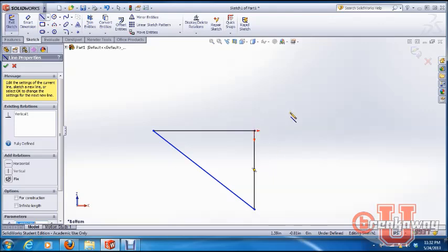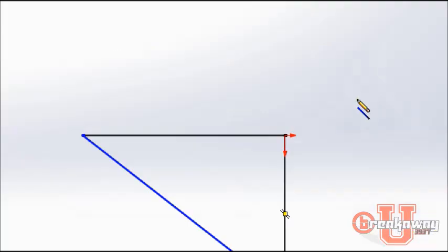Now, for example, let's say you messed up and you didn't want to continue the chain. Well, you can hit Control Z. Well, it usually worked. Let's just do it the old way. Let's do a trim entries here. So I hit trim entries, which is up there in your sketch ribbon as well, and I can just trim off what I don't want.